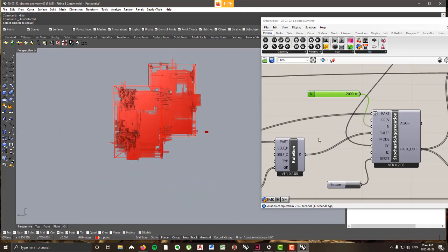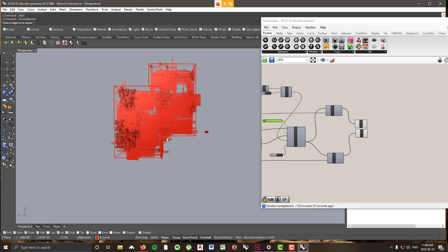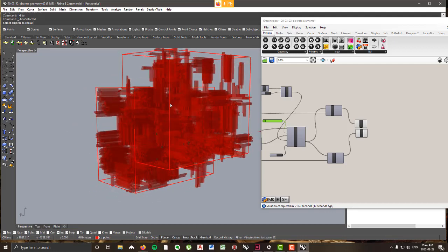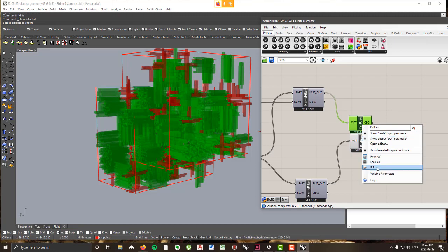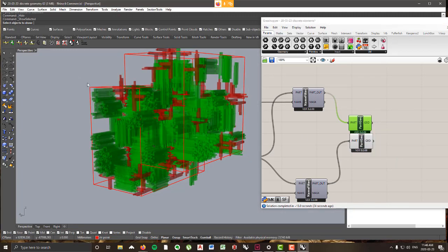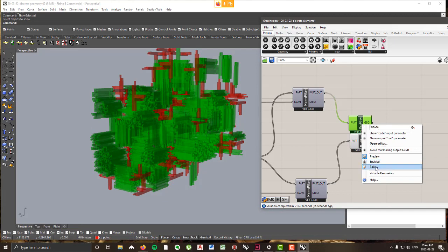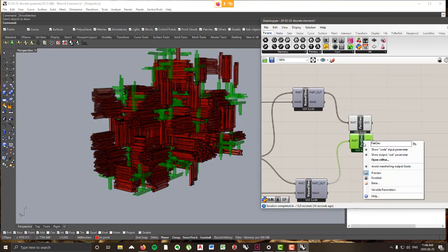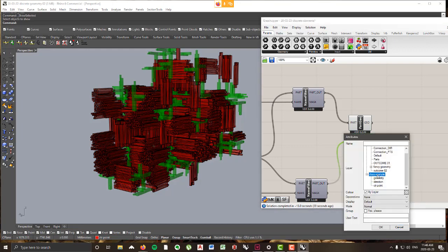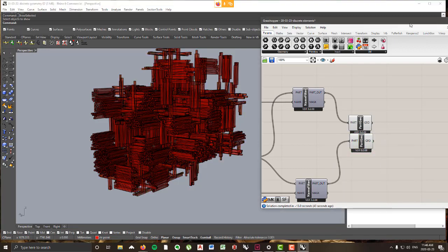In fact, you might want to bake these parts. So we haven't baked anything yet, so maybe let's bake them now. So I'll bake these. So I'll right click this component, click bake. I'll just save on the class example layer I made. I'm grouping it. I'm going to right click the angle points here, bake. Again on the class example, group, yes. I'm going to click OK.